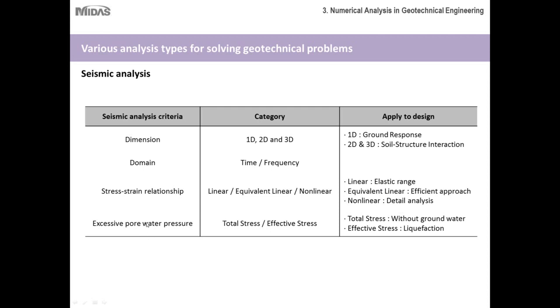are involved. And then excess pore water pressure leads to a phenomenon called liquefaction. So for those of you who are working in California, I'm sure you're very familiar with liquefaction and the complexities that come with it. For those of you who aren't too familiar with liquefaction, essentially what it is, when there's water in the ground and the ground and the water are subjected to seismic loading, the ground itself can act as a liquid, which leads to a lot of considerations to be taken into account for seismic loading.